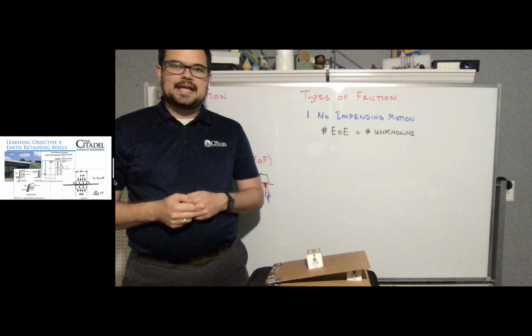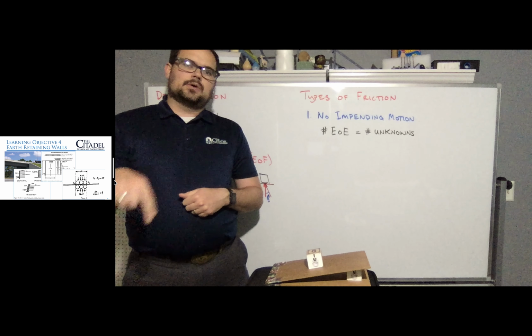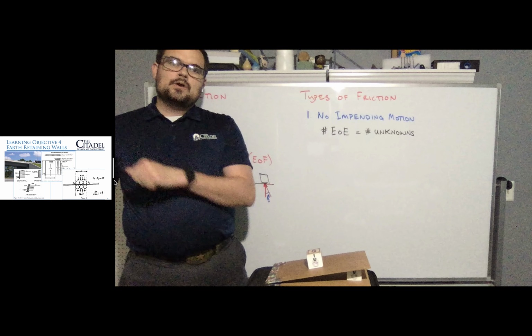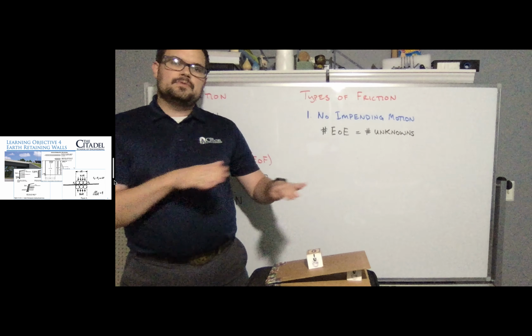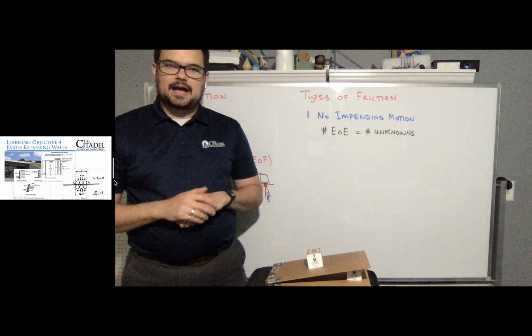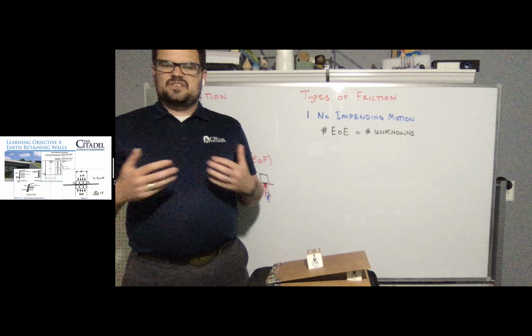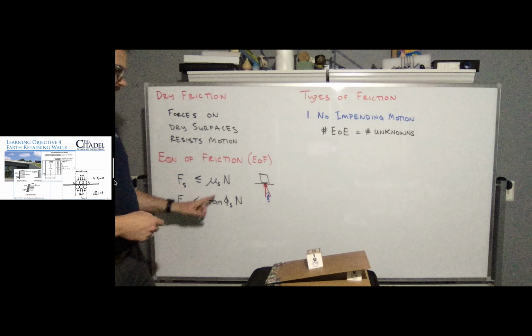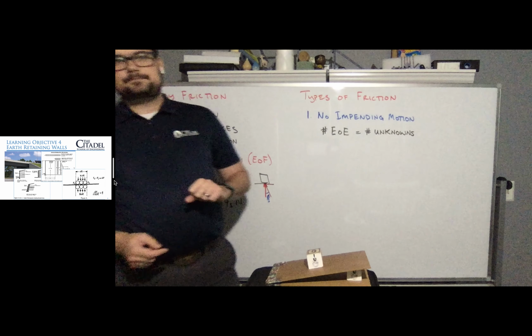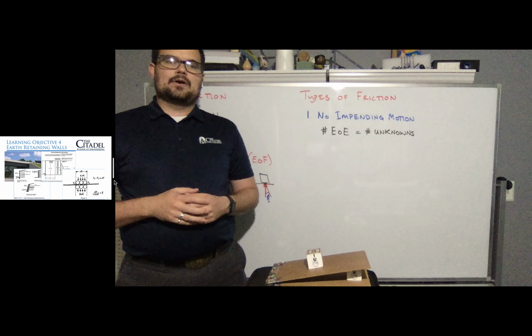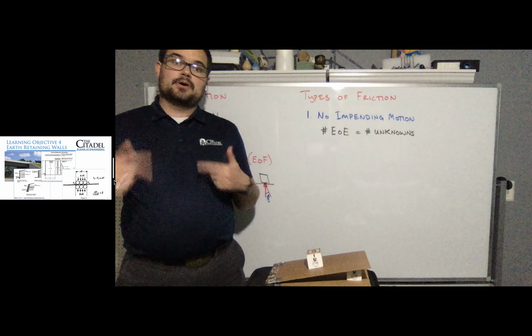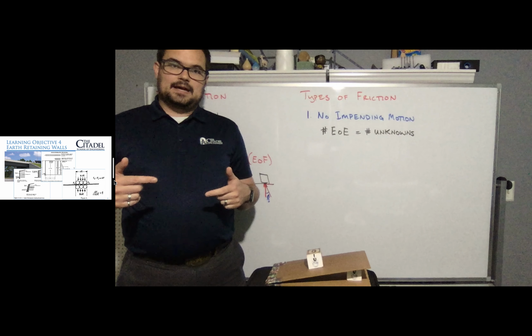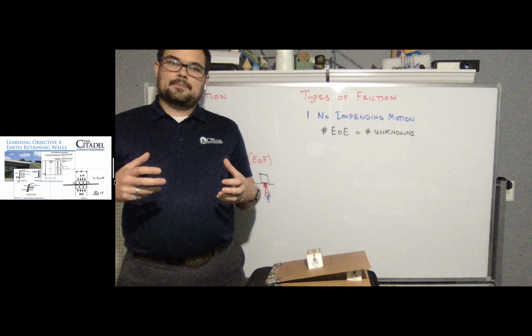It turns out that the coefficient of friction for rubber tires is highly dependent on the temperature of the tire. So this is why in NASCAR during slower laps, you'll see them swerving. What they're doing is trying to keep their tires moving fast enough to keep the temperature up. So the higher the temperature, the stickier the tire, the higher the coefficient of friction. And so they'll swerve like that, or maybe at the drag strip you'll see them burn out right before they pull up to the line. Well, that's warming up the tires.